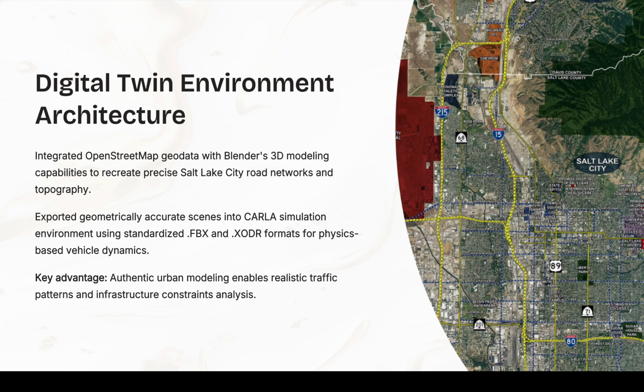Now, to start, I modeled a portion of Salt Lake City. So that's my digital twin environment architecture. I picked sections of Salt Lake City and imported those coordinates using OpenStreetMap into Blender, where we used the Create Road Mesh add-on to create road meshes that mimic the actual urban environment in Salt Lake City. After that, we exported these road meshes into CARLA to simulate it and form the 3D mesh